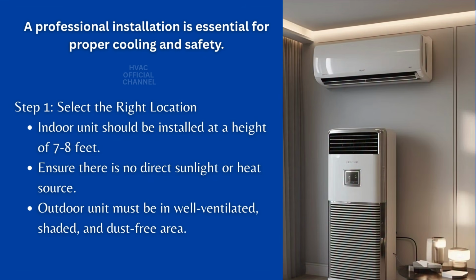Indoor unit should be installed at a height of 7 to 8 feet. Ensure there is no direct sunlight or heat source. Outdoor unit must be in a well-ventilated, shaded and dust-free area.